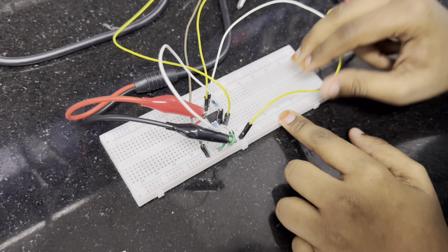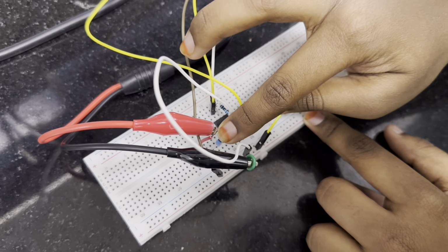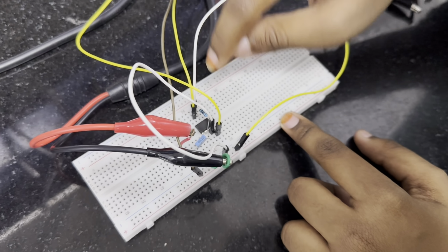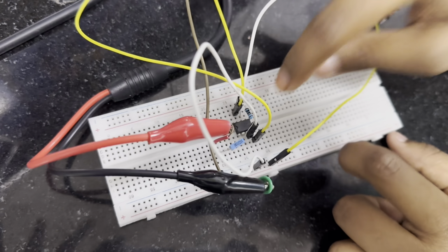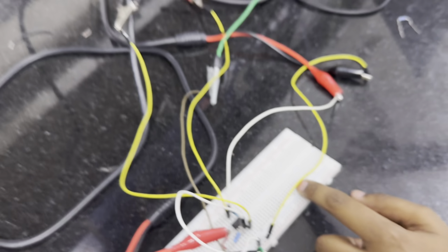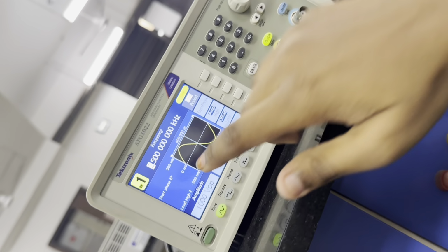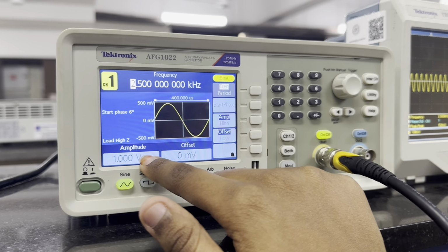Today I am going to explain differentiator circuit. So this is our differentiator circuit, and we have given resistance of 1 kilo ohm and capacitance of 100 nanofarad, and the resistance is connected to the 2 and 6 pins of the op amp, and we have given a power of 12 volts. And when we given an input of 2.5 kilohertz and 1 volt peak to peak, we got this